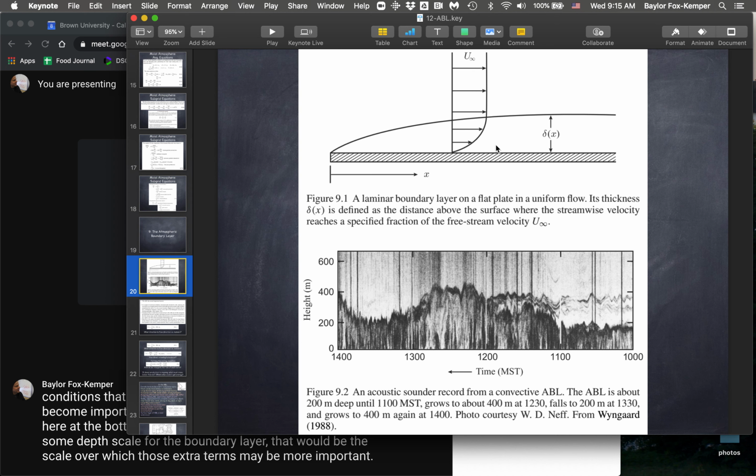This conception was really developed for a laminar boundary layer where you can solve everything and think about the matching conditions between a viscous boundary layer and a relatively inviscid interior. So here you can neglect the viscous terms. Here you definitely can't. And because the viscous terms have a higher derivative in them than any other terms in the equation, they're the ones that require this additional boundary condition of either slip or no slip. This is illustrated here to be a no slip boundary condition.